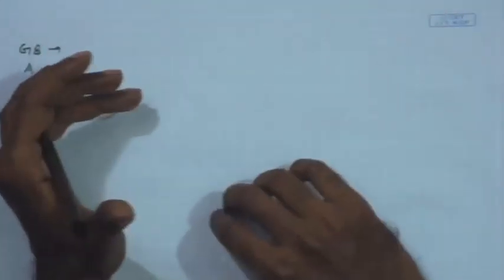Welcome back. Let us resume our discussion on the comparator design that we are looking at. Remember, starting from the ADC specifications, we arrived at some of the important specifications of the comparator. Before that, we discussed some other constituents of the single slope ADC, namely the sampling unit, where we discussed the transistor level details, what are the non-idealities that are going to come when we look at transistor level implementation of a simple transmission gate based sampling switch.